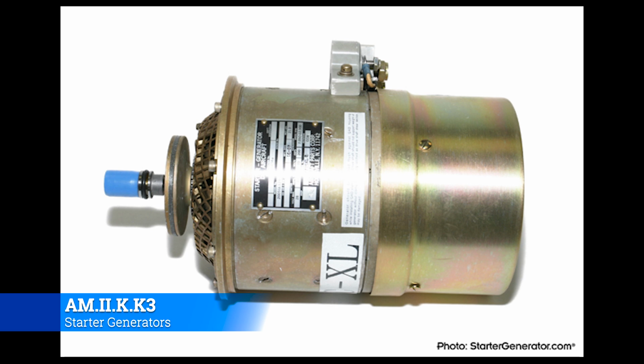All right, so this is the kind of run-of-the-mill starter generator you'll see on a lot of small turboshafts and turboprops. This one is specifically off a Rolls-Royce turboshaft engine. You'll notice that it looks a lot like a DC motor, a DC generator. It's the same thing. It's not really a whole lot to see. A couple of things to point out. If you look, the drive spline there is covered up so that it doesn't get knackered in the process of moving it.